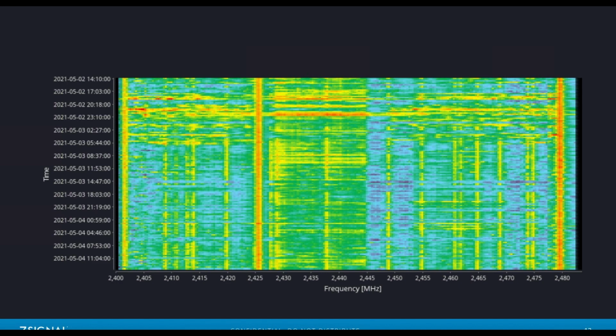And we talked about how Bluetooth, when it frequency hops, does try to avoid the channels that are already in use, but I'm not sure if there isn't some other kind of unknown protocol operating here. Yeah, that's right. And again, whether we know what it is or not doesn't matter. This is going to be disruptive to the Wi-Fi experience, and we need to avoid this. Maybe we can identify what it is, like it's coming from this security camera. We're not going to move the security camera. It's there, it's in its place.